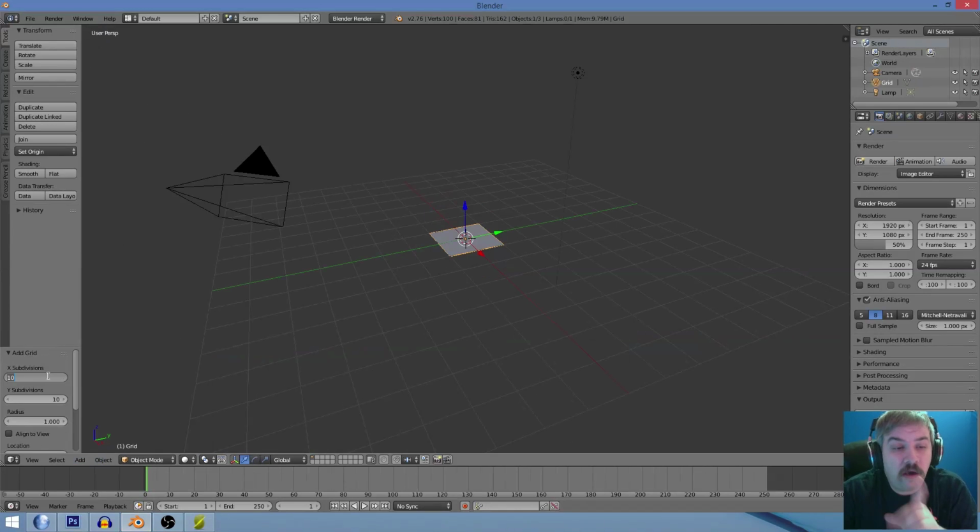The higher you go, and let me just put these in here, I like 300 by 300, that seems to be good. The higher you go here, the more detail your model will have, and your STL file is going to be huge. I did one earlier, I think it was 1,000 by 1,000, and it was like a 60 megabyte file, and most slicers couldn't handle that. So we're going to do 300 by 300.